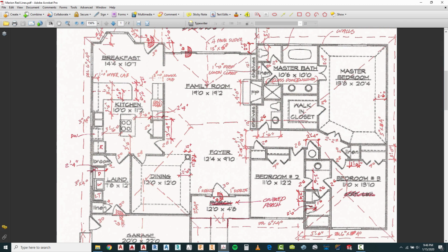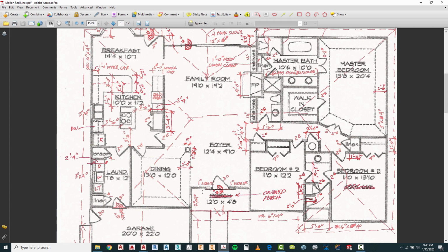Now if you take a look at this, we have this window with 1-foot side lights on each side. I'm going to go ahead and make that part of an entire assembly, so when we tag these doors or window, which means we're going to create a door schedule, a table with them, I'm going to make them part of one tag only. So the windows, the side lights, are actually part of that door.